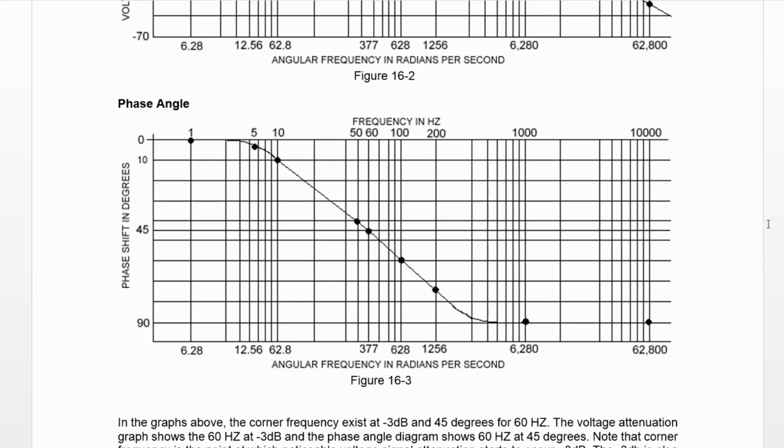Okay, so now we kind of understand what frequency response is and how we use that to filter. And if we didn't get rid of these frequencies, our valves would be going up and down, up and down, and they'd beat themselves to death. They wear out. You wear out the packing gland. You use up the air. You wear out your I to P because it's moving so much back and forth, and you have a lot of consumption of air.